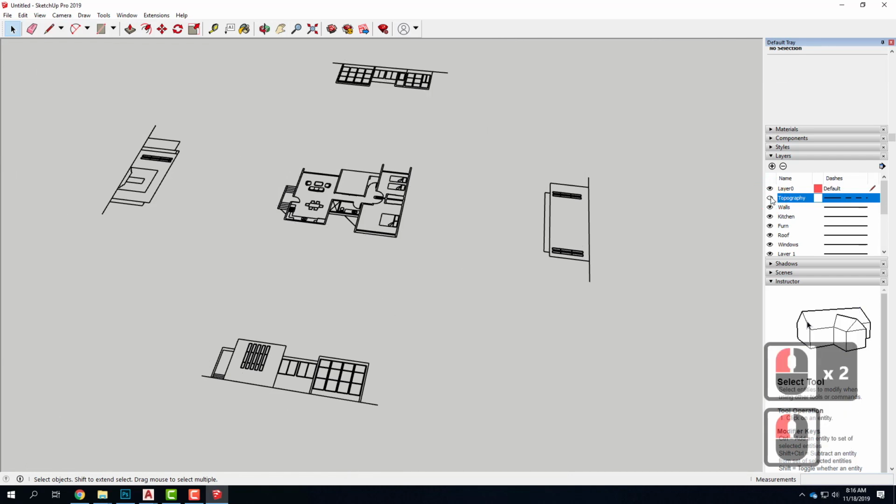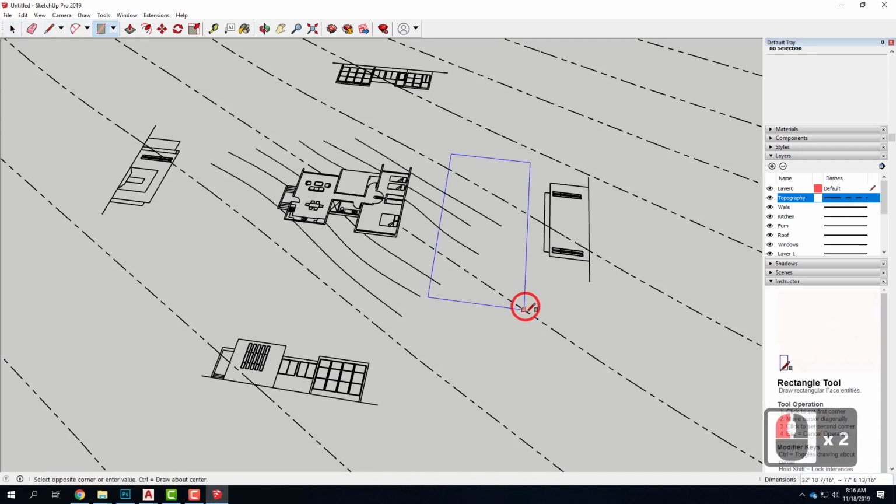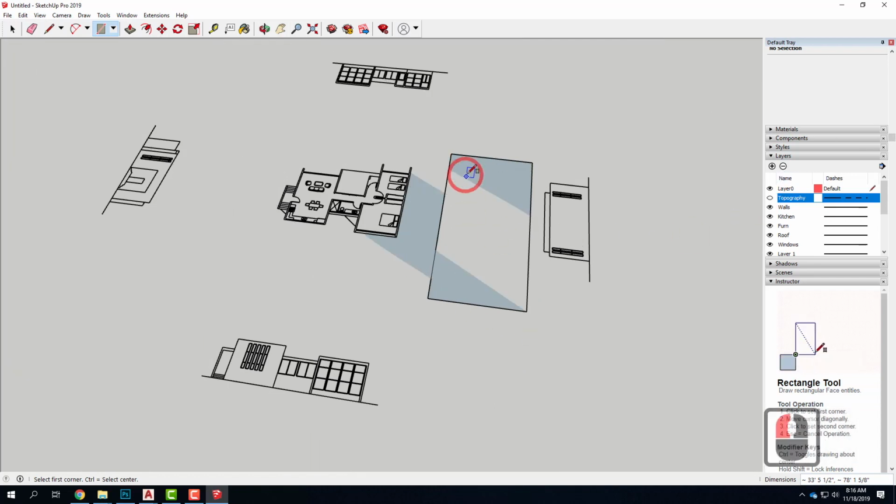The problem with this is that when you turn off a layer in SketchUp, it doesn't remove it from your scene. If I were to still draw, let's say, a box here, draw that box, see how it fills in these odd surfaces? Even if I were to turn off the topography and draw that, it's still cutting up my surface in these awkward ways.